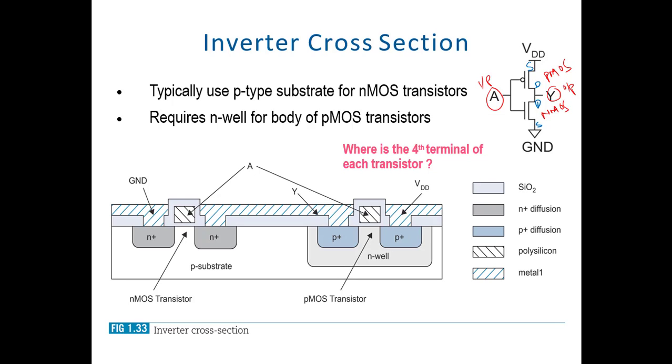If you look at this, here we have the NMOS and here we have the PMOS. We start with the P substrate, which is like our first layer. It is mechanical support for the whole thing, and we start to develop different areas. For example, this area is our doped area, and it has an abundance of electrons. N plus means an abundance of electrons.